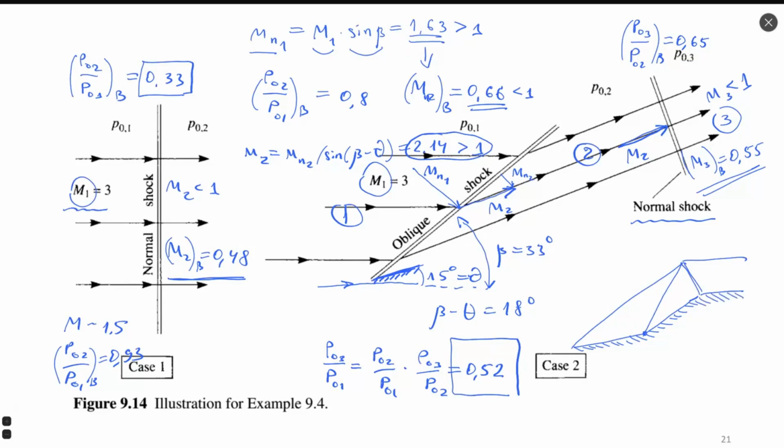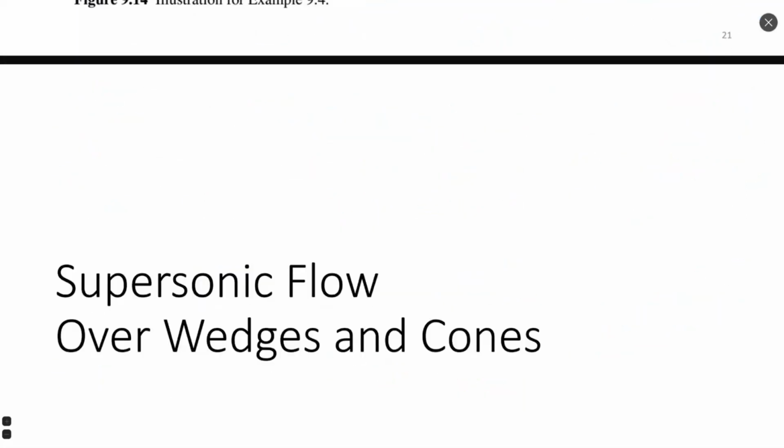In this case, we can find efficiency on transition through the 1st oblique shock wave, the 2nd oblique shock wave, and then through the normal shock wave. Finding the product of these efficiencies, we will find the total. And definitely for the 3 shock wave structure, we'll have much higher efficiency, can be 70, 80, 90%, depending on optimization of angles.